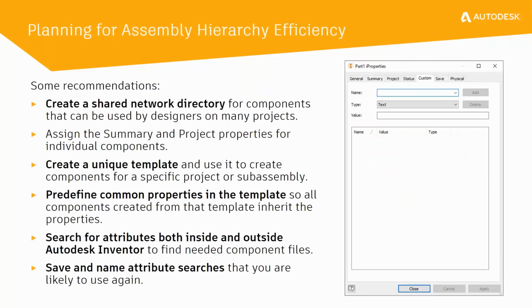Some recommendations when it comes to planning for assembly hierarchy efficiency. Create a shared network directory where components can be located and used by designers across various different projects. Create a unique template that can be used for a specific project or subassembly. And inside of that template, you can even assign common properties so that any components or assemblies or drawings that are created from that can automatically inherit the properties from that template.